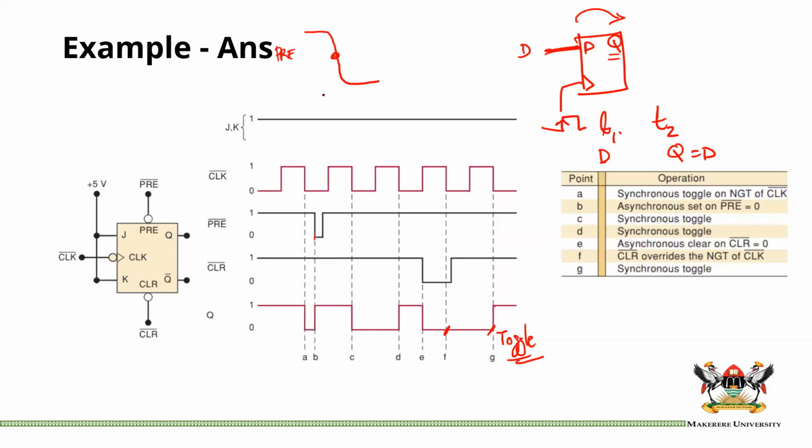But you are presetting, meaning that the transition is going from 1 to 0. That's your preset, and that is your output. Once you give that command, it will take a bit of delay before the output goes through its 50% point. So this is exactly similar, but in terms of pre and clear.